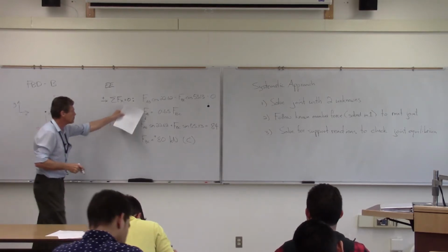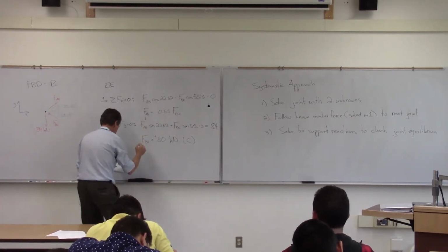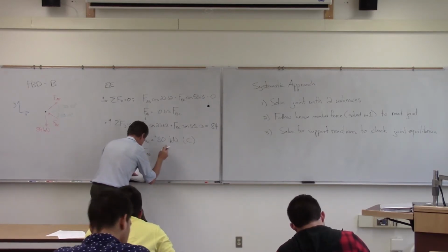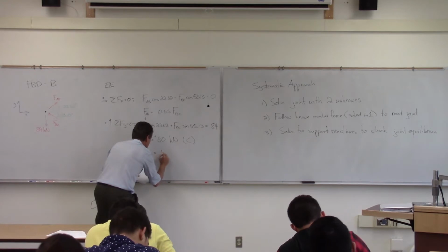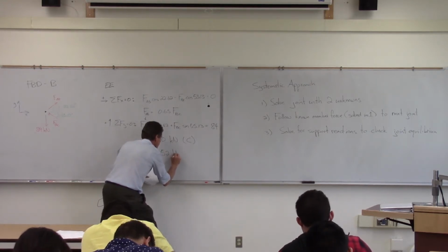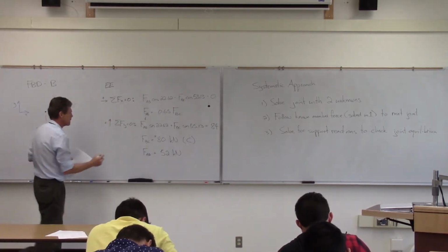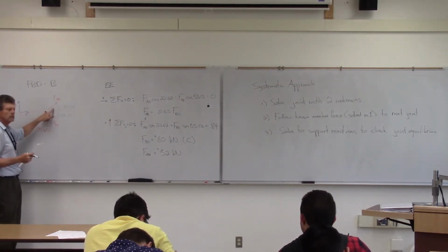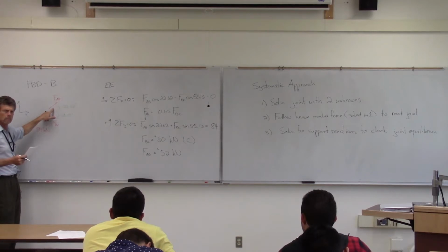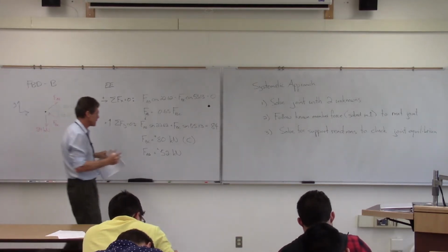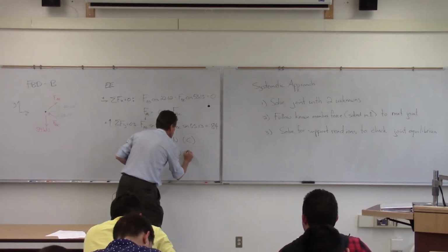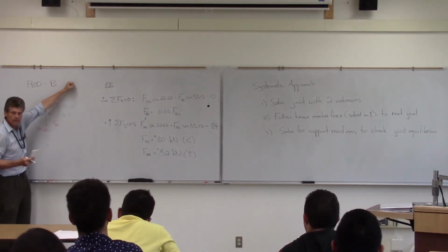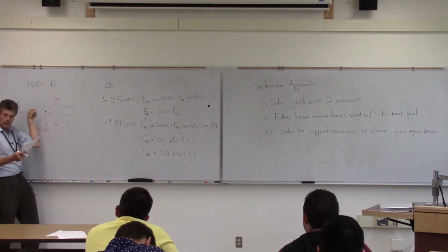And then going through my substitution, I can shove that back into there. And it comes out with a positive quantity. What is that member doing then? It's the opposite. It's got to be in tension. It's pulling on my joint. When we think about the member out here, it's going to be pulling back.